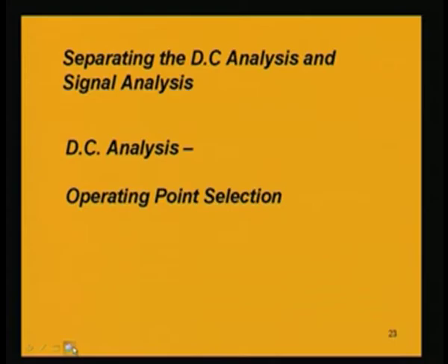So, now the amplifier as such is amplifying an AC signal, and it is having a voltage gain given by minus Gm into Rd, Rd being the resistance at the drain, and the minus sign is signifying the phase reversal.